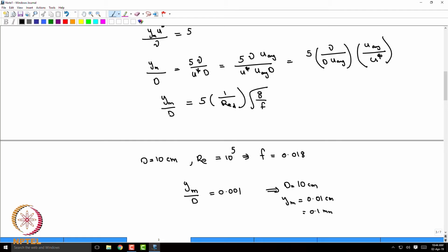So it's really thin. One thing is that, remember, yesterday when we did the calculation, we threw away all that thing that was coming from the wall layer, and the overlap layer, the logarithmic law, did very well. One reason is this, that the contribution that's going to come from it is extremely small. Second is that the thickness is so small that if you start zooming into the thickness of that wall layer, would you see the roughness or not?